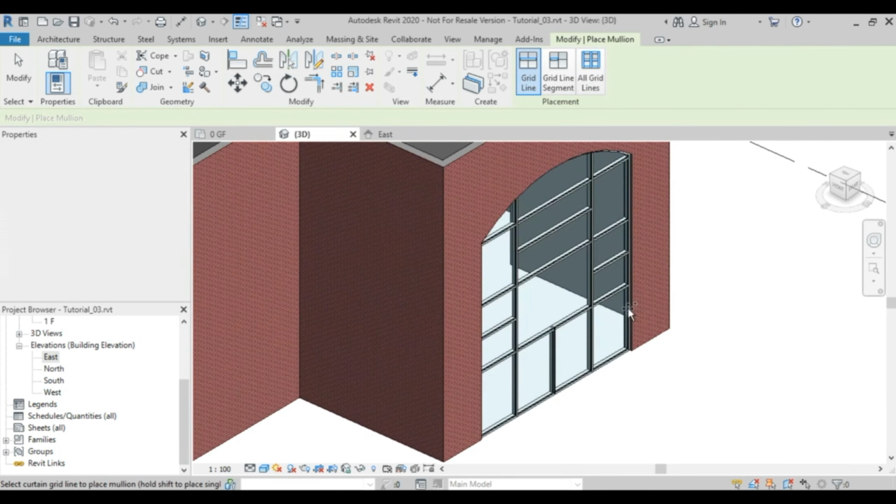And as you can see right now, they are built inside my work. So I'm actually playing around with how things are done and how I can cut my curtain wall, which was one single piece of glass, into 2 parts, then change the profile to an arc shape, then add mullions if you want to.